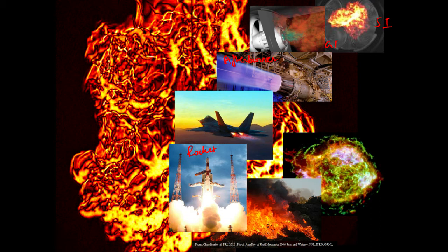So, in nature and engineering, you see combustion not happening in a very smooth, quiescent, and laminar manner like you see in a Bunsen flame. Rather, it happens in a very distorted and convoluted structure because the embedded flow in which combustion happens is invariably turbulent. So, it can be safely said that all these aero propulsion engines, these gas turbine engines, afterburners, rockets, scramjets, etc., involve combustion in turbulent flows.